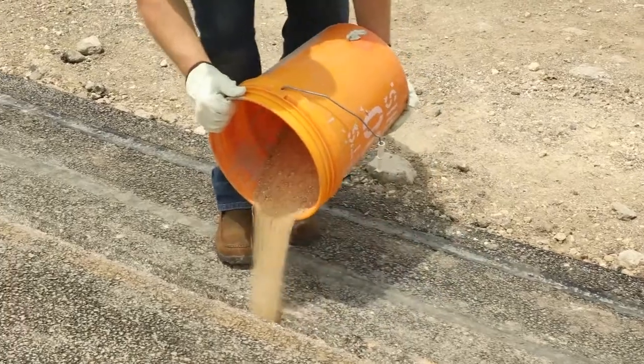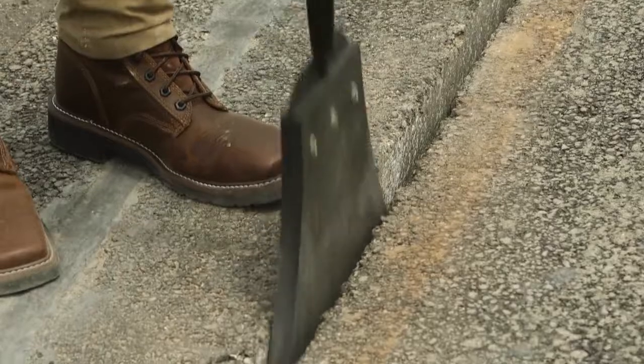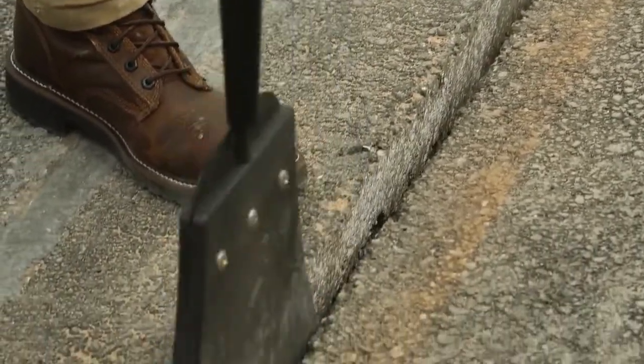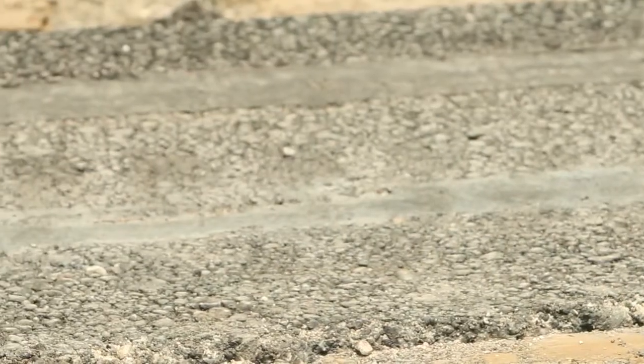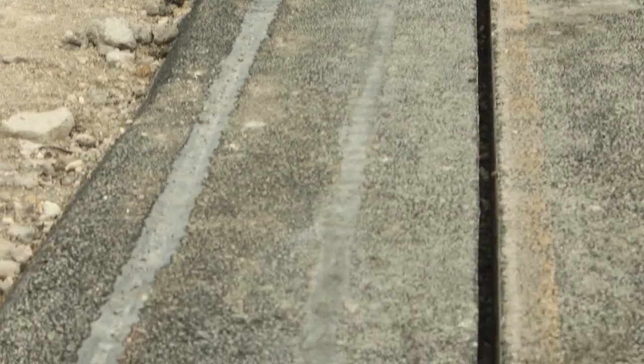Backfill the trench 2 to 3 inches at a time, tamping between each layer to ensure equal pressure on all sides of the conduit. Ensure the backfill utilizes dry soil or time for drying prior to sealing the microtrench. There are 2 reinstatement material choices.